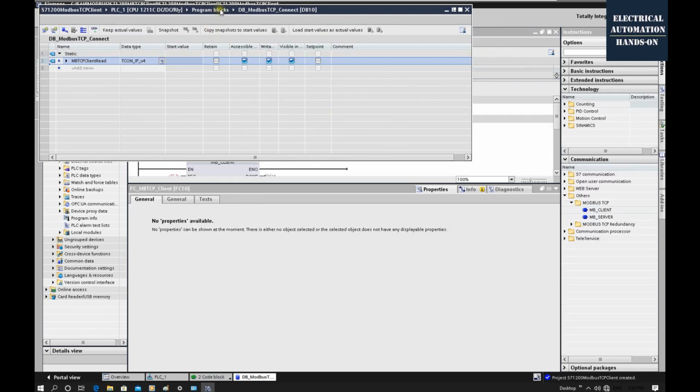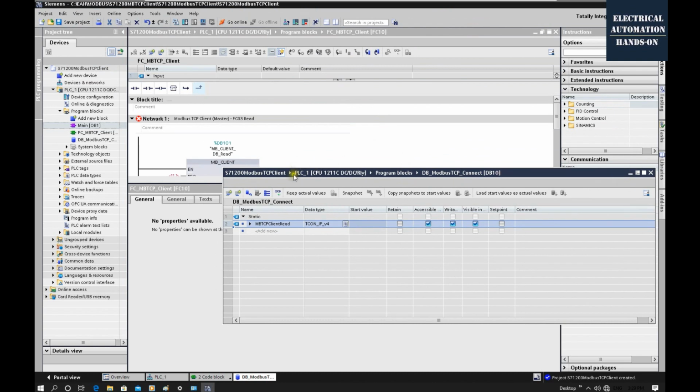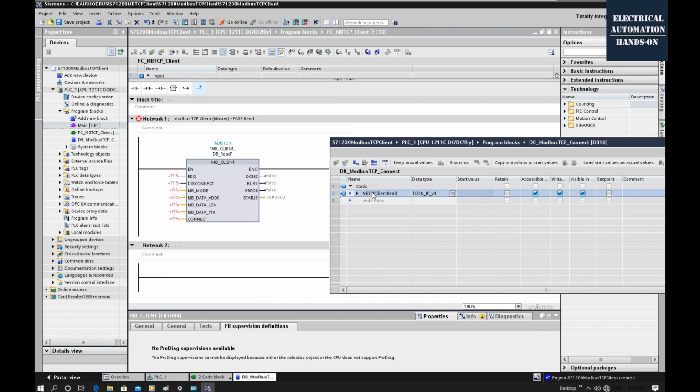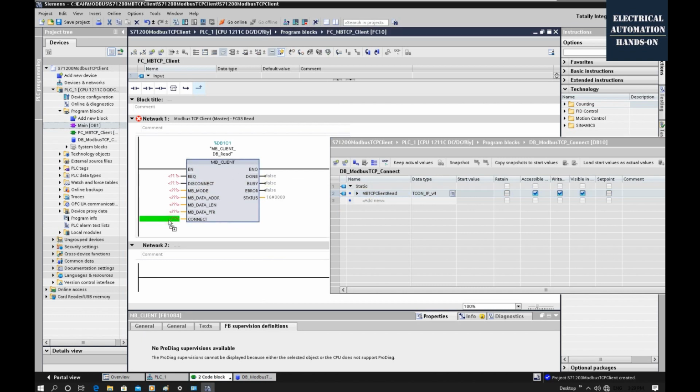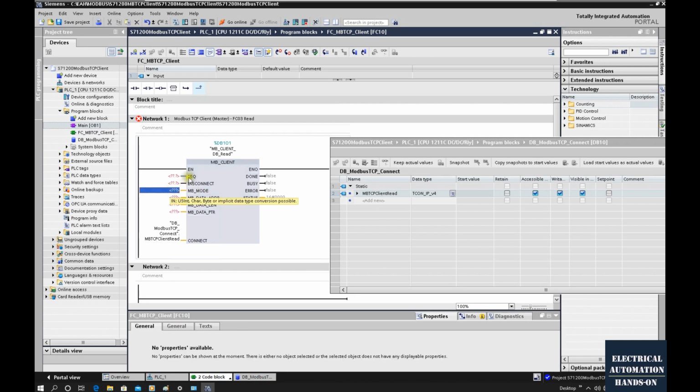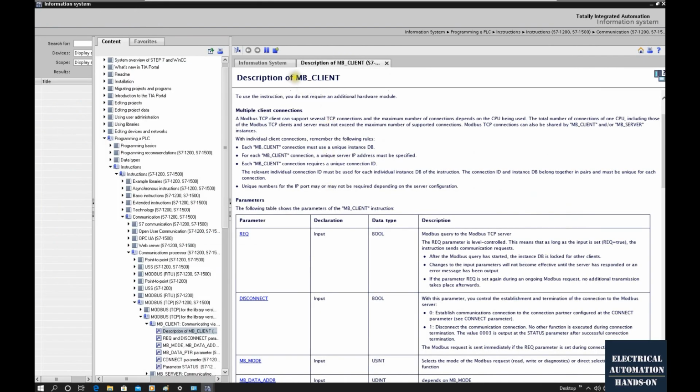And then we can float here, click this button, and go back to this function here, and we can drag this variable to here, release. This basically transfers those parameters to this connection here. And then the Modbus mode. So let's check out the detailed explanation for this. Let's click this function block and hit F1. This is the Modbus client function explanation here.